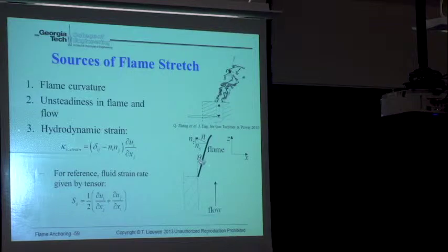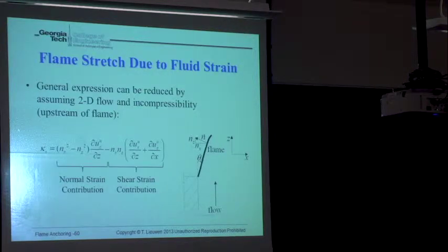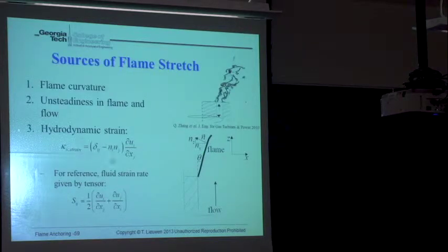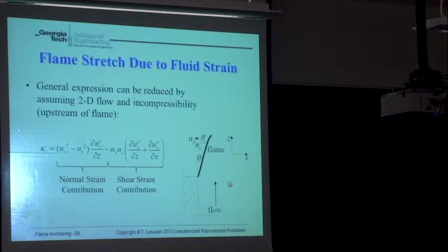The flame is going to be spreading at some angle theta with respect to the flow. And what I can do is, I'll just do some math. Okay, so I'm going to skip the math for you, but let me just take this expression and chop it apart, decompose it into different components. And by the way, my coordinate system is going to be z is the axial direction, x will be the transverse direction. So if I do that, the expression for kappa S looks like this.